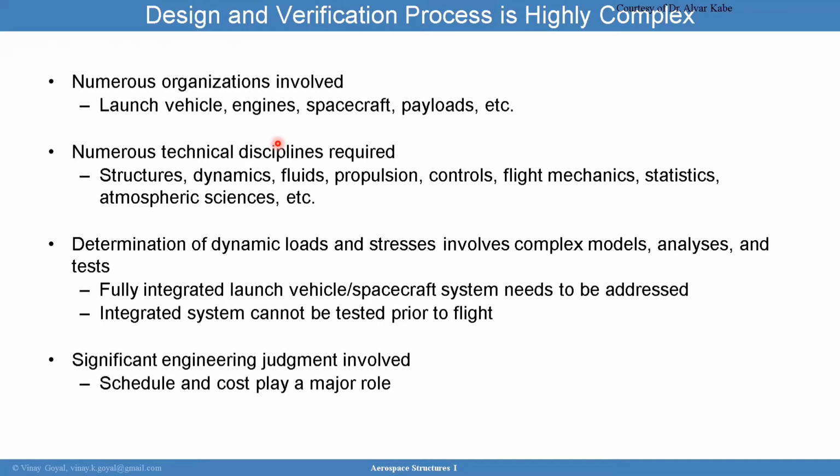The determination of the dynamic loads and stresses involves complex models, usually dynamics, and a fully integrated launch vehicle spacecraft system needs to be addressed. An integrated system cannot be tested prior to flight typically. That would be very difficult to do. Before flying, I can't really test the full system together. You may have tested the structure structurally, but what about the whole structure as a whole and how the dynamics interact with the whole structure as a whole? You can't really do that before flight.